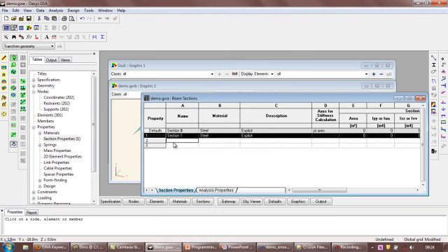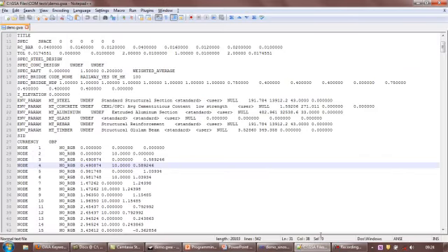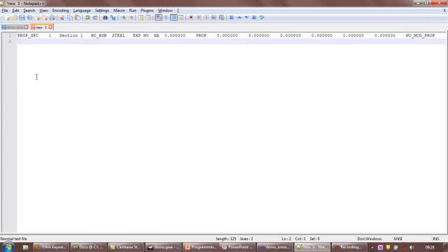If I go to a text file and paste it here, what I get is a string that stands for the data that we copied. By sheer coincidence, this string happens to be in the GWA format. Well, actually it's not coincidence, it's just that we use the same GWA engine for various features within GSA, for example copying and pasting data, or for the text file, or indeed for the GW command, as you've just seen.